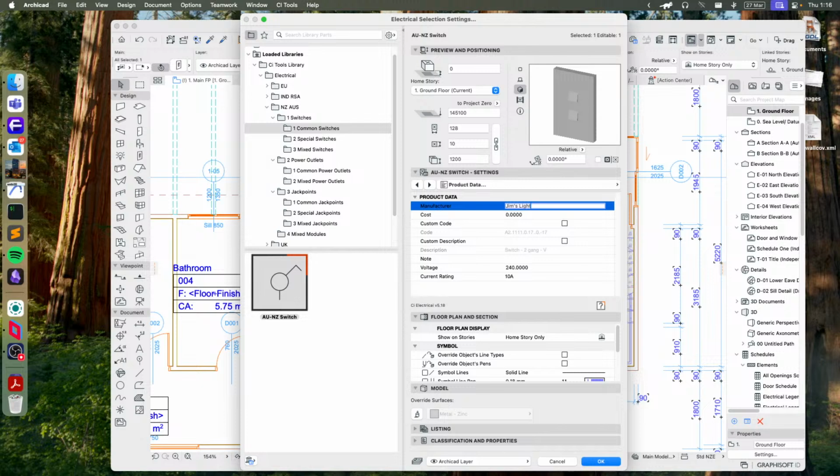So you can see in my preview here that it is showing where the reducer will be. So if we want to reduce at this point, we draw to the reduction amount that we want and then click, and then the same on the other side. So the matching hotspot on the other side will give us a reducer inward there as well. So we can reduce in whichever direction we need to.